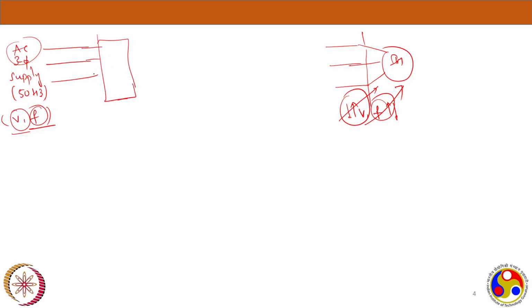So this is like an AC supply I'm giving here, and this is the bridge rectifier. I'm getting a DC here, and there should be another level, because if you see the voltage here is fixed. There is no variation in the voltage, no stepping down or stepping up. That's not happening here. It is just converting my AC to a DC. So the voltage is again fixed, but I need a voltage variation and also a frequency variation.